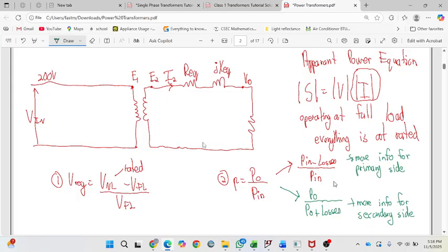And that's all. That's literally how you will know which one to use. If you have I1, V1, you have your input power, which means you have your power factor. You just use the Pn form of it. And if you have V2, I2, your load, which you get a power factor from your load, you will just use that one, right? No matter which one. But just use the one that you have the most information for.